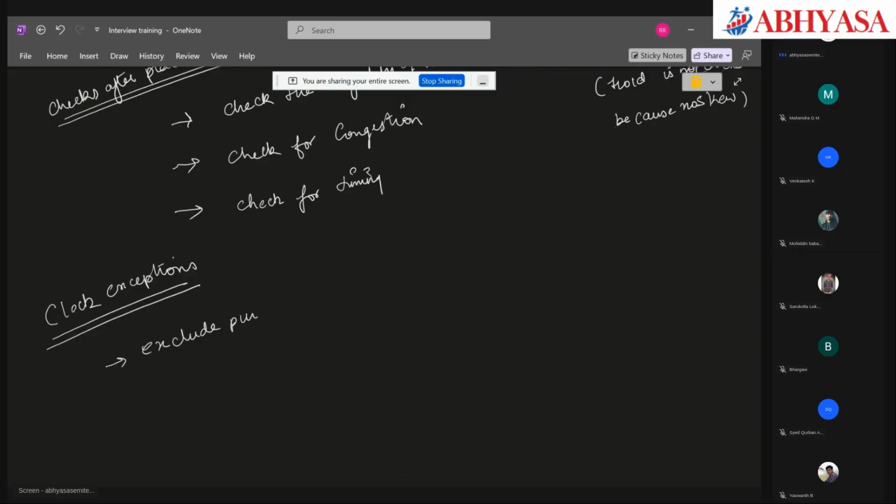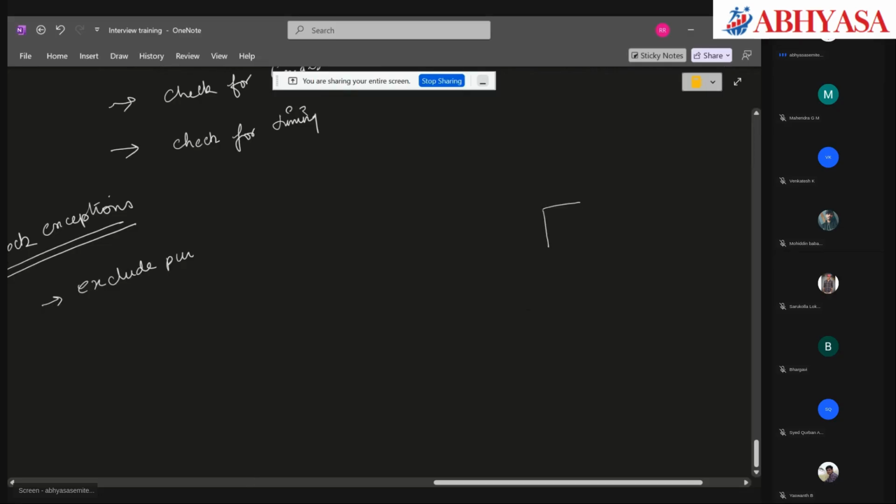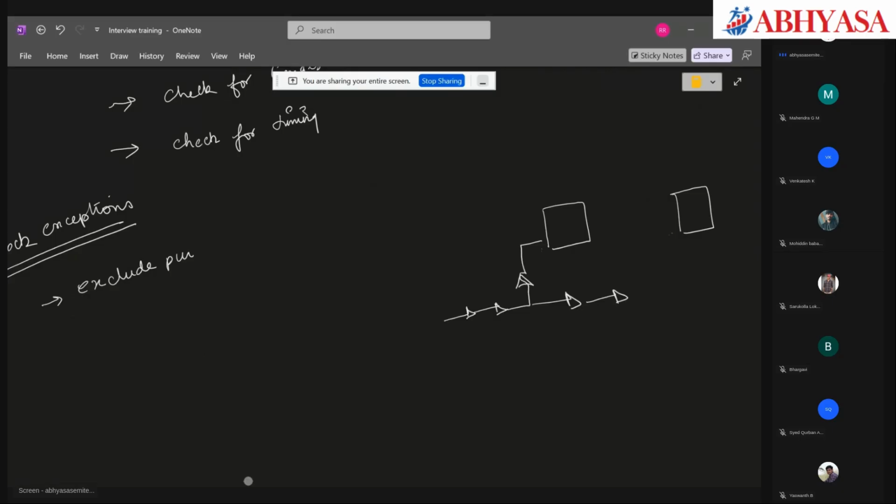First let us look at what is happening in the clock tree. When I build a clock tree, the tool will buffer my clock path. What are the factors the tool will consider while buffering my clock path? One is skew. Next is latency. It is not only these, it will also look for transition and cap.